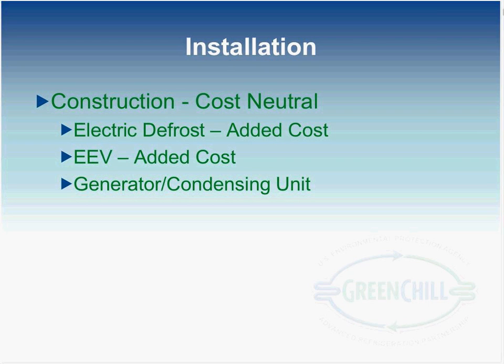So we did put in a little bit of an added cost for the electric defrost, not from the manufacturer, but from the electrician wiring the electric defrost. Our standard criteria is to be hot gas defrost, so this was an add for the electrician. A mistake here on the slide: not the electronic expansion valves. I meant to put the solenoid valves here. There was an added cost from an electrician for wiring the solenoid valves.